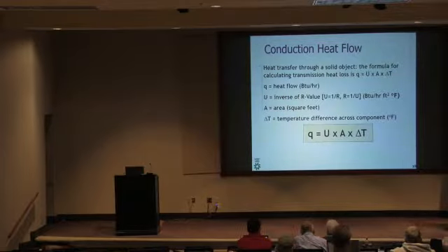So we have actually had engineers who are like, explain the spray foam roof line to me, because if I just do Q equals UA delta T, the spray foam roof line doesn't work as well as the insulated ceiling. And the answer is, it's called reality. It's called how things get built in the real world.